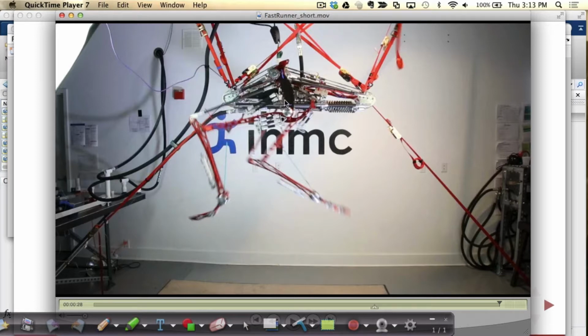So it's an extremely underactuated system, one actuator per leg, and an extremely complicated system where the number of possible hybrid modes here, we counted as 4 million or something like this, because every one of those little clever mechanical designs meant a new joint limit, a new clutch that was engaging or not engaging. These were all hard limits, impact events in the system.